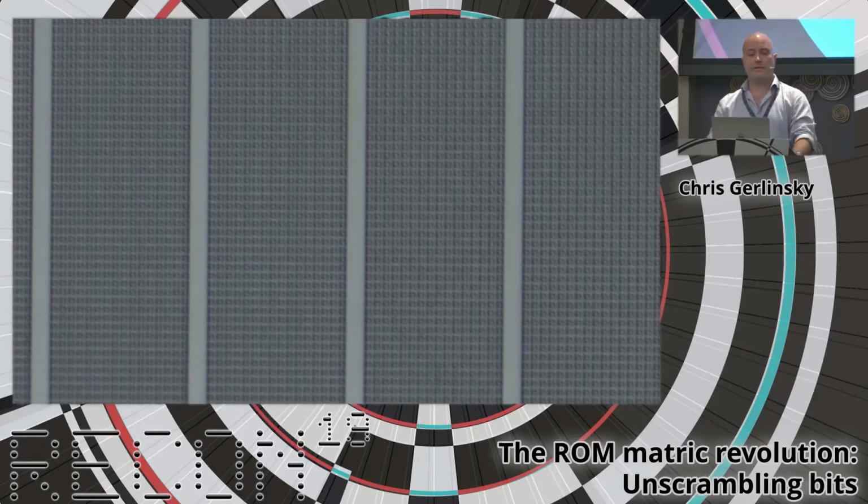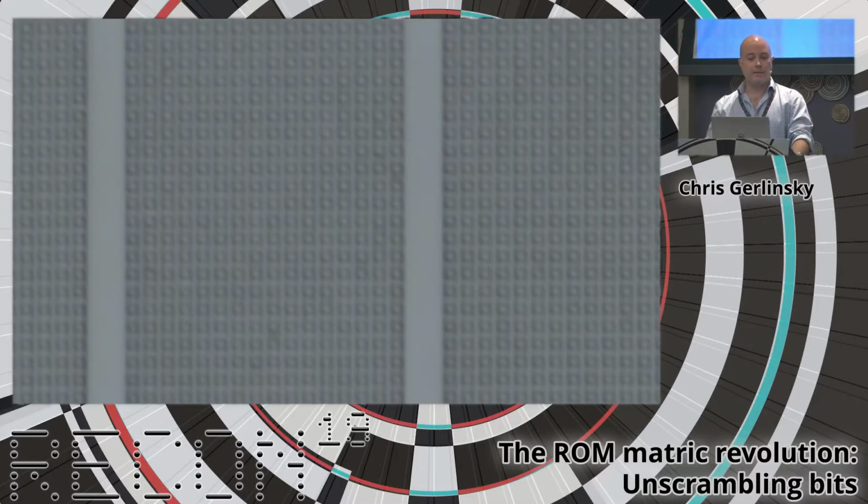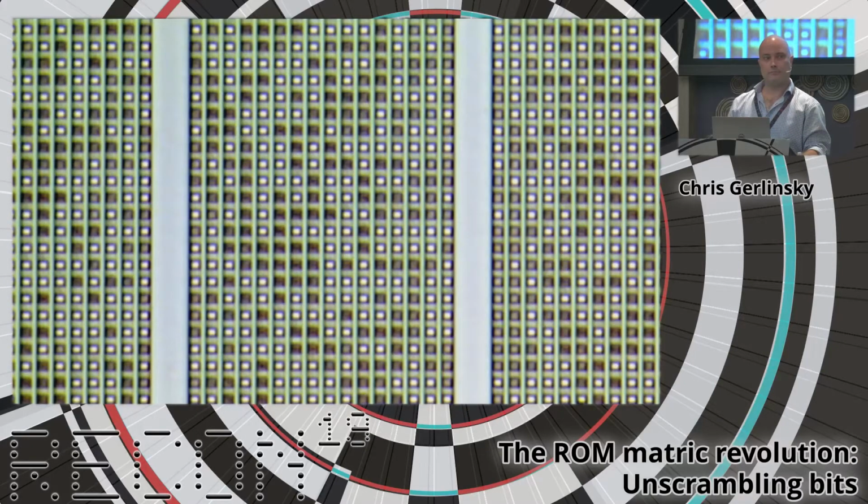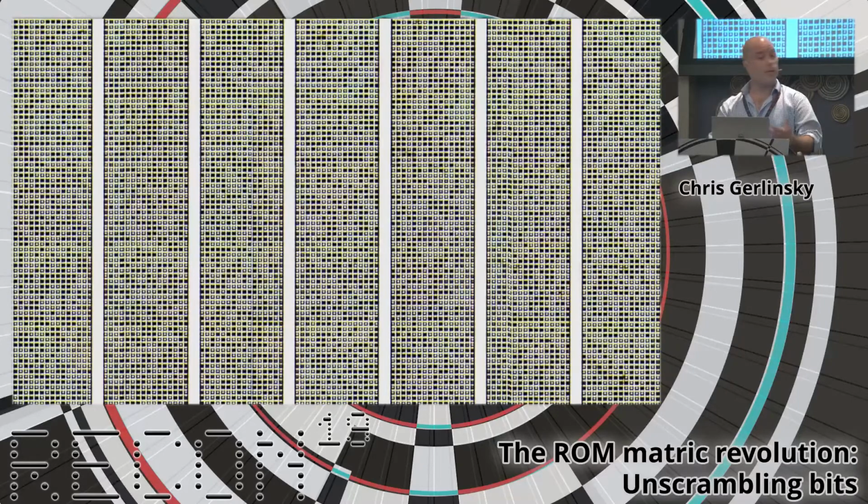So starting out looking at one of these ST19 ROMs, this is what it looks like after removing the top layers of the chip with hydrofluoric acid. Zooming in a little bit, so we can see the rows and columns of bits, but we don't actually see any data there. It's a little bit of a fuzzy picture, but also there's no contrast between the bits. After doing a selective etch on the ROM, a dash etch it's called, now we have some contrast within the bits, and we can actually extract the bits visually from this image. Wider view after doing some contrast adjustments.